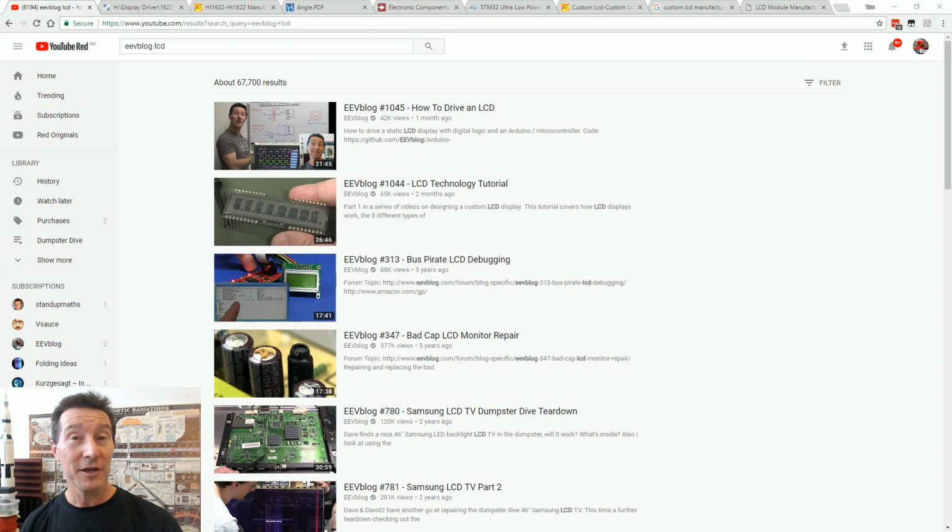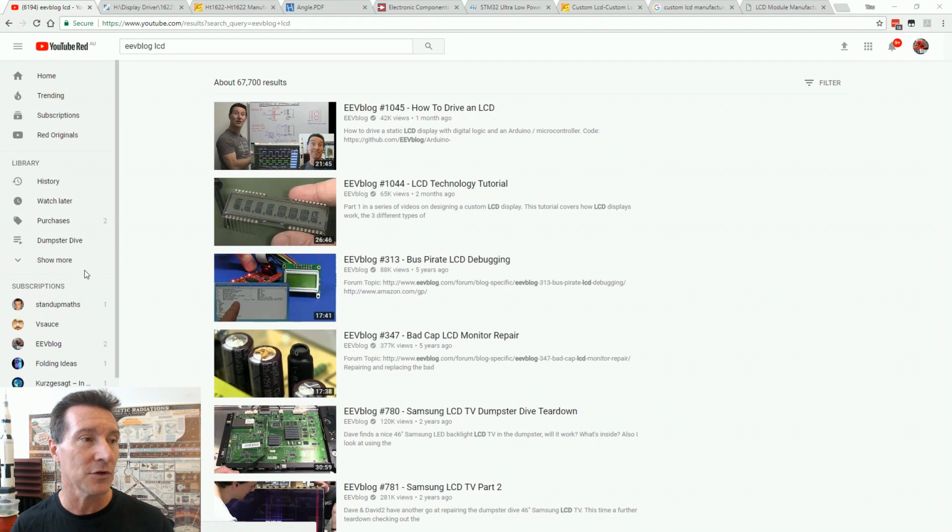Okay, so you've decided you want a custom LCD because it's going to make your product look more professional, gives you something that you can't get with a dot matrix LCD, gives you better viewing angle, better contrast or whatever, or you're simply trying to save costs, which is often a dominant reason. That's why a $1 watch or a little novelty gadget has a custom LCD in there, because in volume they're cents each, especially if you're making 100,000 widgets. So cost is often a big driver.